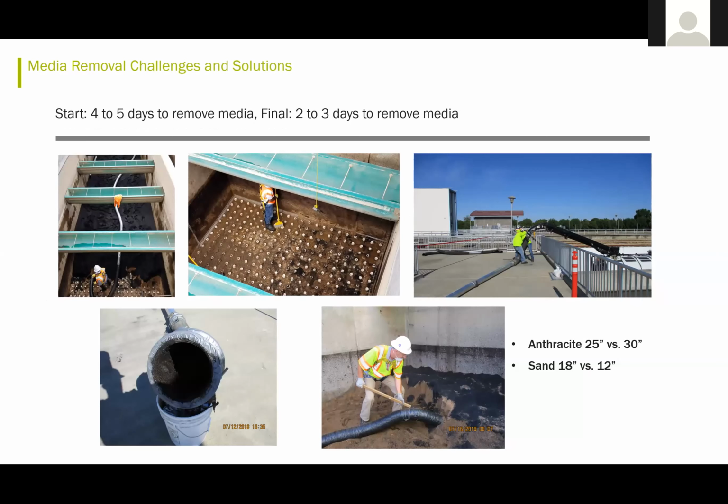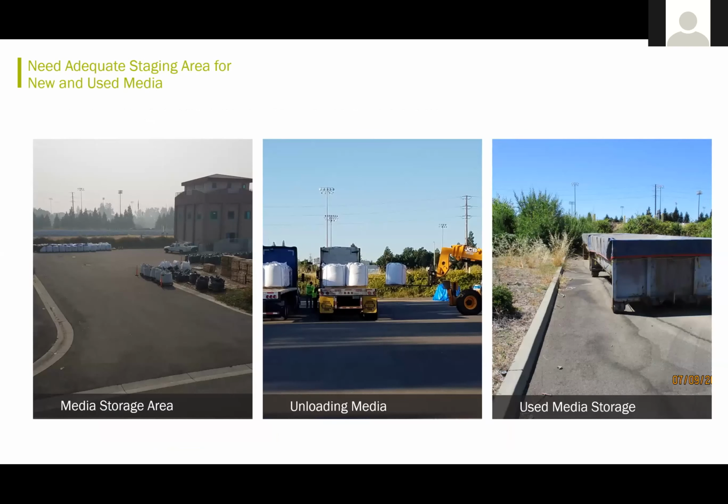So when they first started up, it was taking about 4 to 5 days to remove the media from a filter, and by the time they got it down later on, they were able to reduce that to 2 to 3 days per filter. And so they were staging the media on site. They had several areas set aside for unloading media as well as for used media storage.